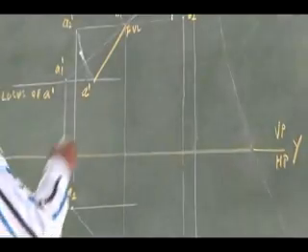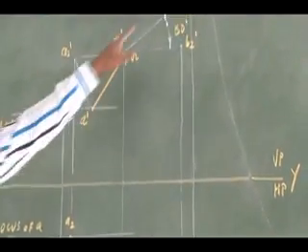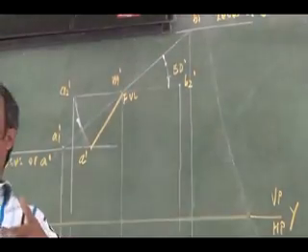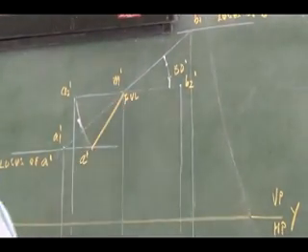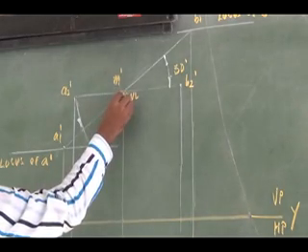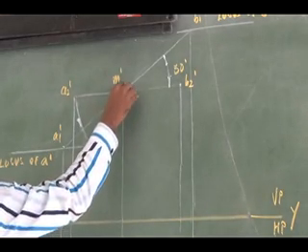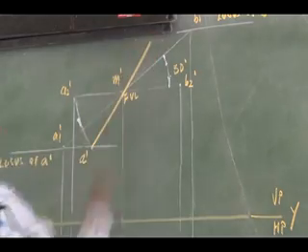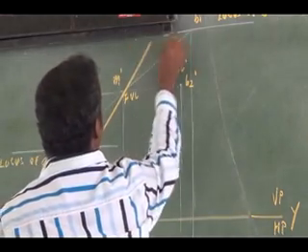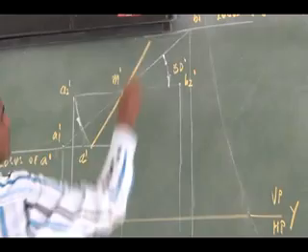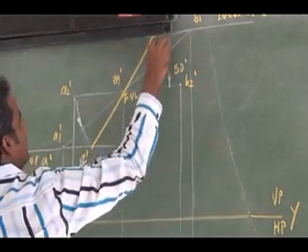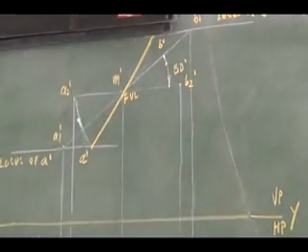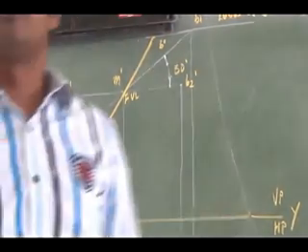In the same manner, if I extend it, it will meet the locus of B dash. So I can get another half of the front view projection. See here, in the same manner I am extending it. So it will meet the top locus, that is NB's locus. So that is going to be my B dash. Is it clear?